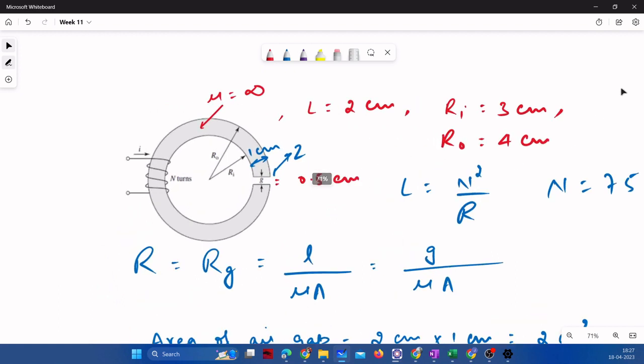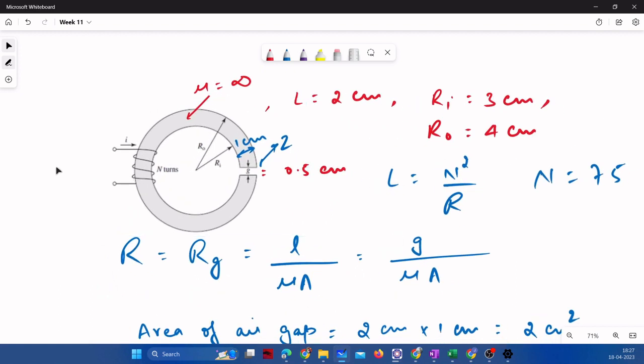See this kind of core. Here the inductor is having that gap. We have to cut the ferrite toroid in this fashion. Core material is almost similar, so its permeability will be almost similar. But to vary the value of inductance, if you need a certain value, you cannot do much on the core.